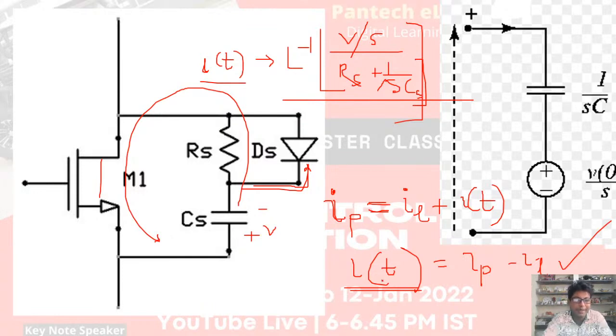While charging, the capacitor should charge very instantaneously, there should not be any resistance in the path, so that's why it will follow this path. While discharging, the current should get restricted, so that's why during discharging, this diode will be in reverse bias. It will discharge through the resistor, so that you will not get the impulsive current. This is called power circuit protection, which is very much used in motor control. So this is the design aspect. So today's lecture is all about this.